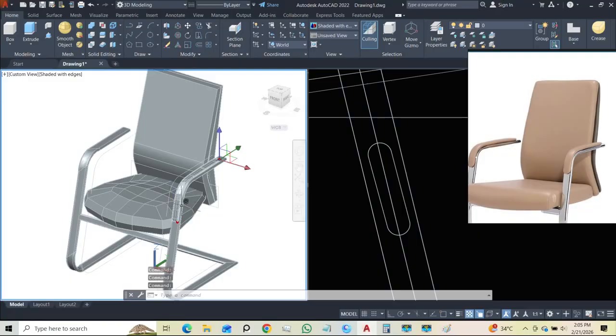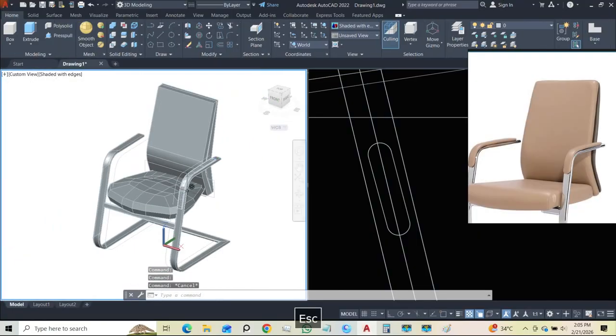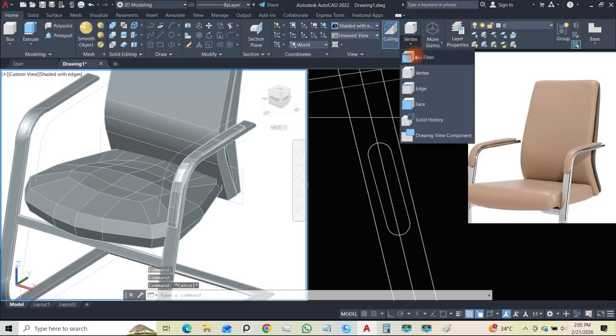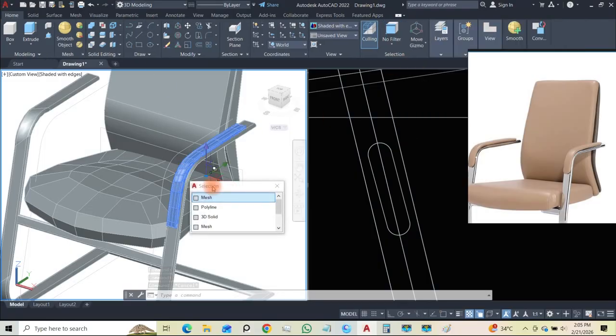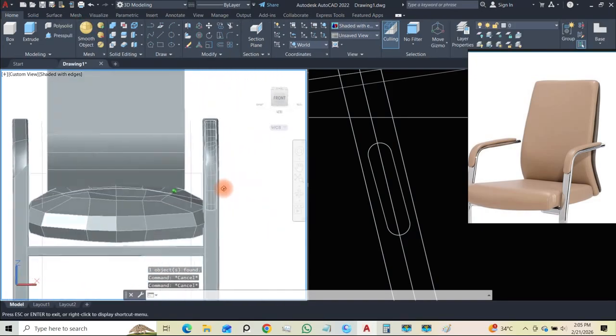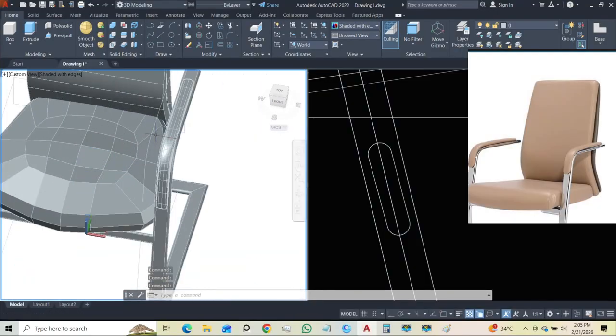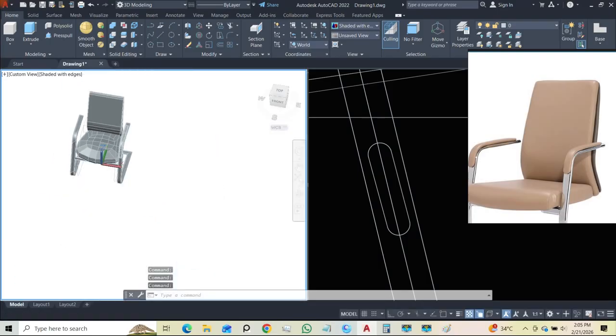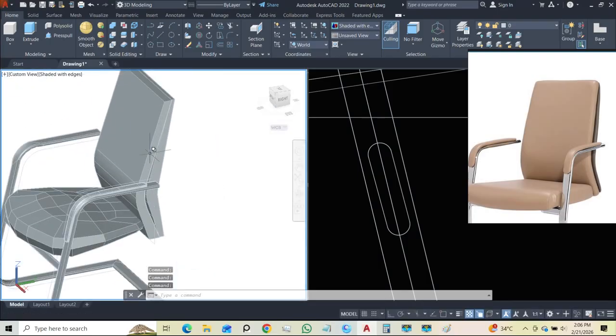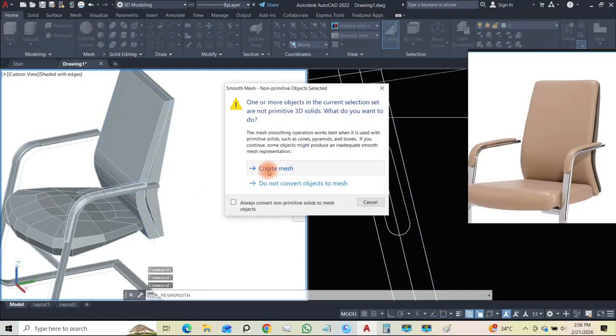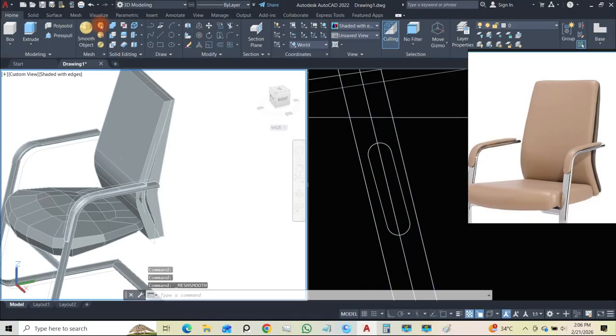Another thing you can also do is, if I have this, just select it first. Let's smoothen it one more time. Smoothing that, so you have a smooth mesh. Okay, so we can just select this and mirror it to the other side, and we're done. So let's see this. If we select this and we refine, convert it to mesh, smoothing a couple of times.